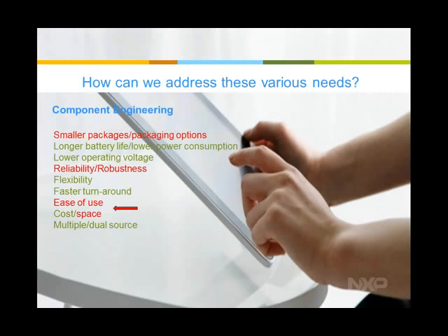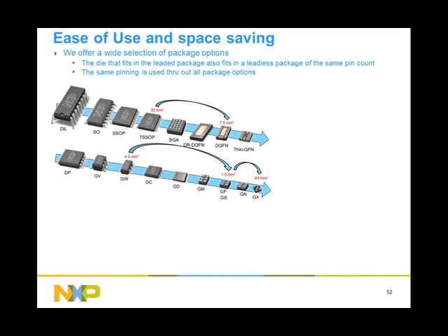Okay, so now moving on down to ease of use and space. As I previously said, the die that fits in the largest package also fits in the smaller, leadless package of the same lead count. And we also use the same pinning. So pin 1 on a TSSOP, if it is an input, is also the same input on pin 1 of the DQFN package.